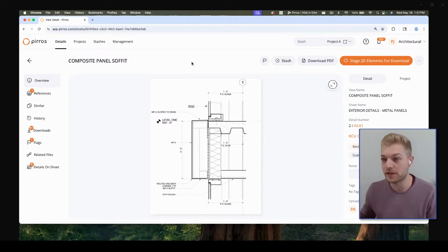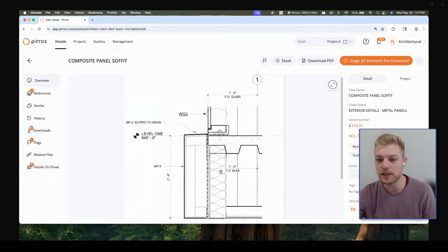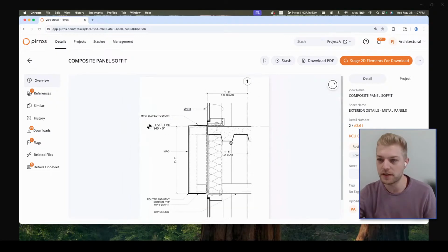All of those details have to be siloed between projects because you can't put that in a Revit container file or in a content management system. So the workflow here, first and foremost, is people seeing how the details have come together and using this as a knowledge bank, referencing these live details. If you find a very similar detail, I can just one-click grab all of those components rather than having to find 8 different components within my content management system. We already have the 8 within this detail. Let me grab them all in one go and copy and paste that onto my new live section cut, my new project.